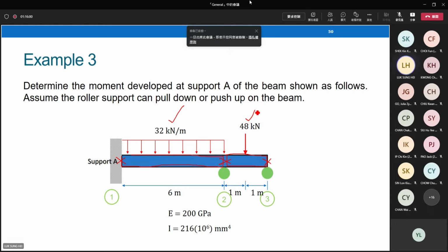We have to convert them to fixed end force vector, Q0, and then put it into our force displacement relationship. Here we use fixed end moment, the concept, the picture that I showed you before, to handle this problem. We have 2 intermediate loadings because they are applied in between the 2 nodes.